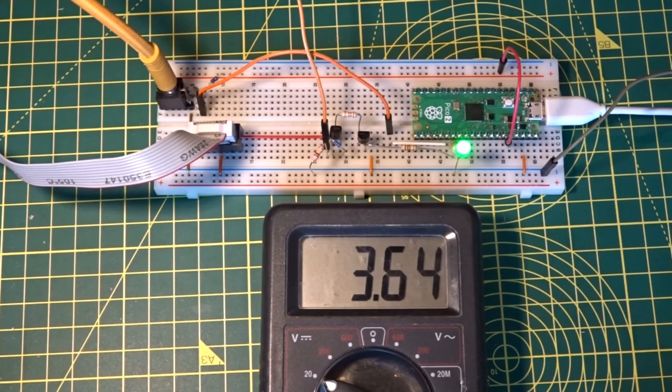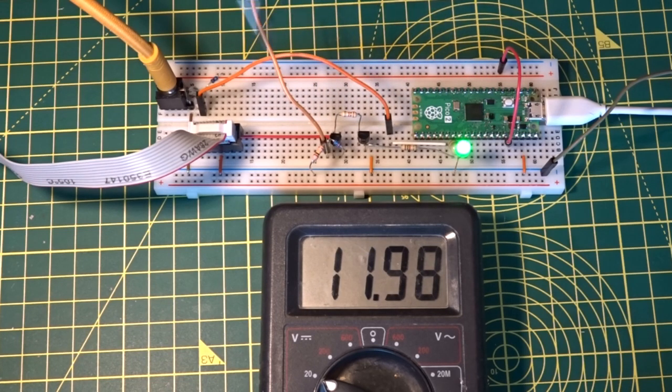I've mocked that circuit up on some breadboard, so here I've got exactly the same clock input circuit that I used on the revision 1 board with a little NPN transistor, and here I'm connecting the output LED directly to the clock output pin on the Pico, and this jumble of resistors and NPN and PNP transistors form the kind of double inverted output buffer for the clock output signal.